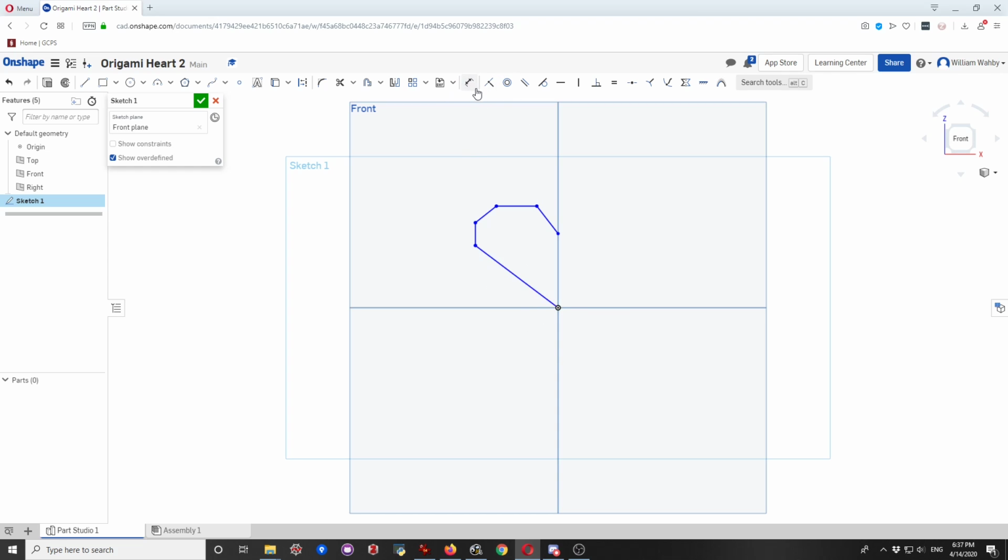The other way you can dimension things is, again, go to your dimension tool, and I'm going to dimension between points. So you can see you can either hover over a line and that whole line will turn orange, in which case you're dimensioning that whole line, or you can hover over a point. If you hover over a point, you're going to select your start point and your end point, and then you can kind of constrain between them. So I'm going to choose my starting point here, and then the next point I want to dimension between is going to be this point here. You can see I hover over that, that turns orange. I'll click on it. And now I can pull to the left and tell it how tall I want this to be, or I could pull straight down and say how wide I want it to be, or I could pull diagonally and choose just the total length of this line segment.